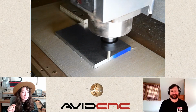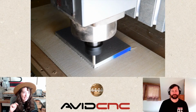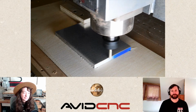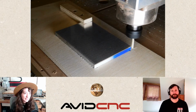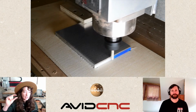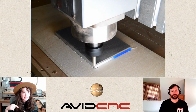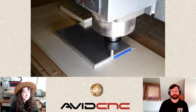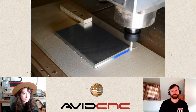So here's the first, this is the east side. This is the pocket toolpath that has the smaller pass step and step over here. It's really nice that you have that blue edge, you can really see the material that's being removed. And we will end up cutting into the plywood here because the aluminum is sitting in that pressure fit. I do add the second clamp on the other side once I have this edge relieved, because there will be no pressure on the east side of the material at that point.